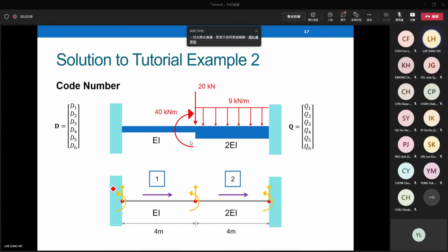Because this time we do not have those special support sliders. Here are well-defined supports, fixed ends. At a fixed end, we have no displacement, no rotation. So at the middle, we have unknown displacement, unknown rotation. The middle is a free end. So you can find the unknown displacement positions immediately at the middle. The others are 0. You can assign code numbers at the middle first: 1, 2, and then 3, 4, 5, 6 for the remaining 4 arrows. This one is quite straightforward.